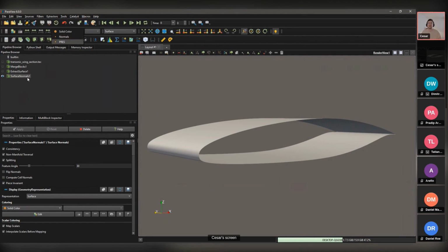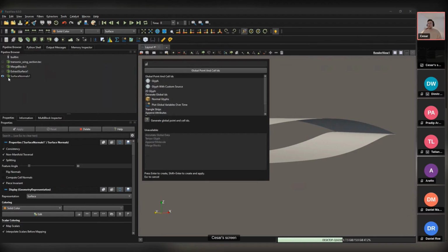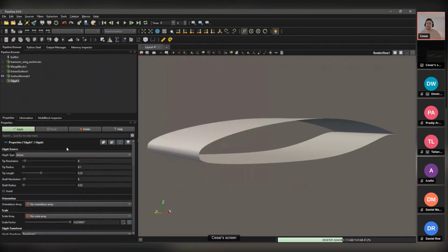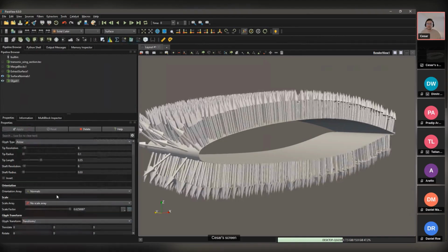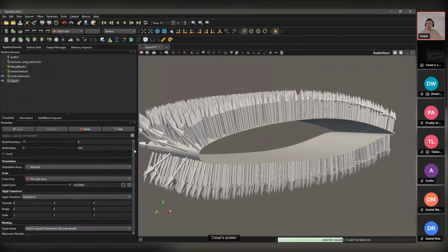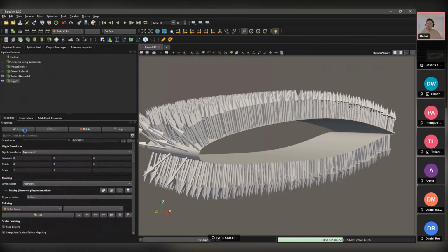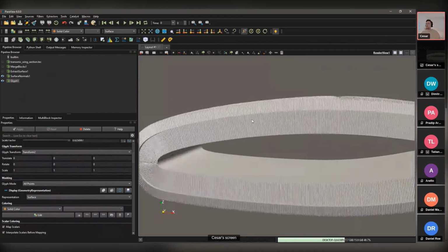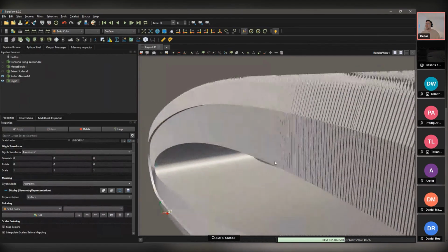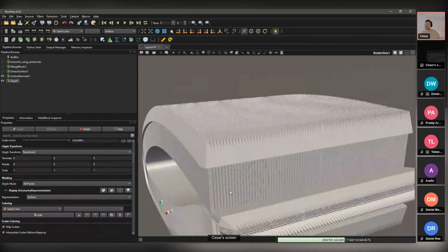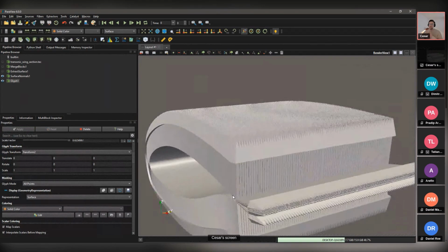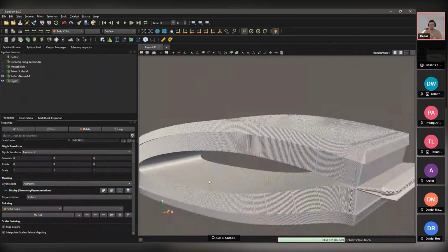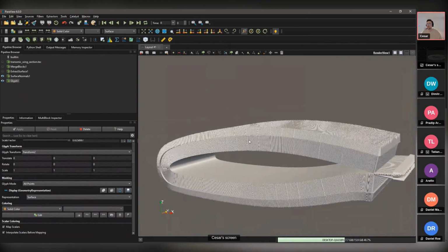We can see them by using the glyph filter. For the orientation array, we want normals. Let's see how it looks. Voila. Now if we select all the points, what this filter does is create an arrow for every single cell, like the normal vector. All these arrows are pointing outwards of the surface, which is going to be essential because later on, when we compute the local force, we have to give an orientation which is going to be normal to the surface. So it's going to follow this vector direction.